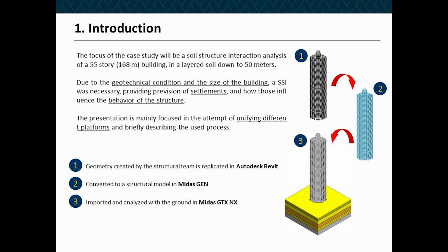So this model was fully created in Autodesk Revit. With the Revit MIDAS Gen link, the model was then exported to MIDAS Gen, and after applying some conditions on Gen, the model was finally exported to MIDAS GTS NX, where the full model was analyzed.